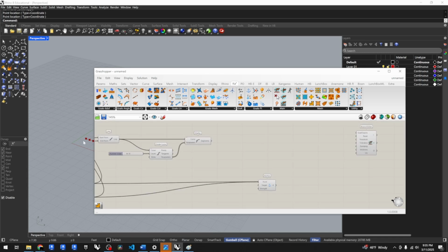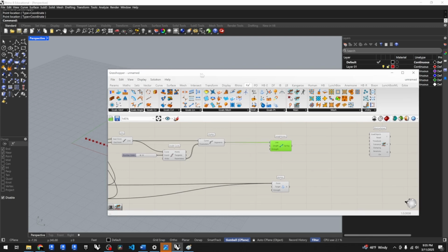Next, as discussed, I want to make sure that these lines can't just explode indefinitely. So if I go to my goals in lines, I can set a length. And this length line goal is very similar to a spring. So I can adjust it accordingly. And so for those lines, I want to bring in the segments that I have for each one of those.